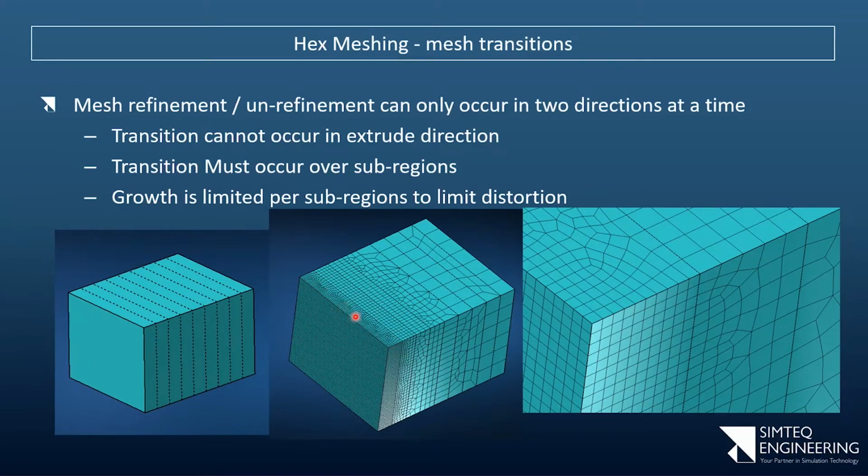So I go from a fine mesh on this edge to a coarser mesh on that edge, and then it's extruded in that direction. If I zoom into this region, you'll see these really nice elements over there, but as you move in that direction, the aspect ratio starts getting worse. So if I then specified a mesh seed from there to there that says fine and coarser, yes, this element will be closer to square there, but this edge will now still be rectangular, and that one in that direction is also rectangular. So it will still be this squashed kind of an element.